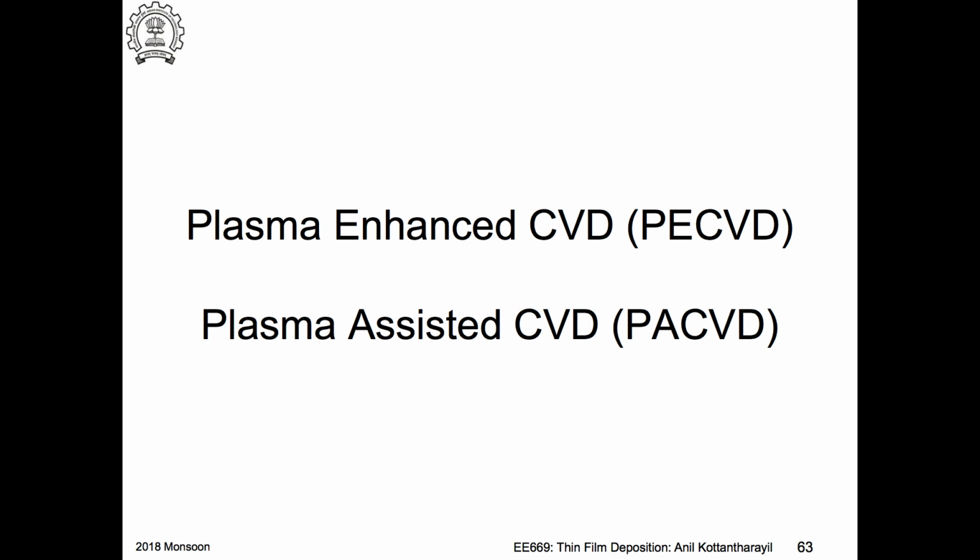Okay. The problem is that if you have NiSi and you heat it, it's sitting on silicon. It will react with the silicon, and then that will become NiSi2. Okay. So what is happening in that process? It's eating silicon. You can see this, right? But you have a junction that you have formed. So if it eats the silicon, it's going to go closer to your junction. Junction becomes leaky, your contact resistance goes bad, so overall not good for devices.